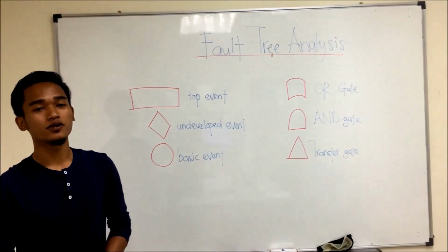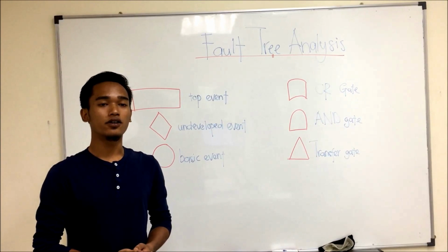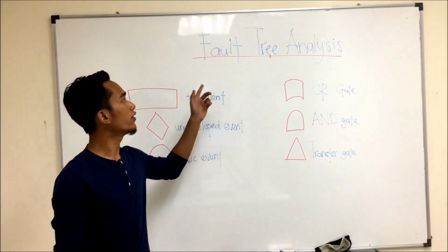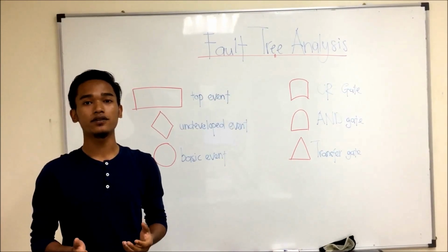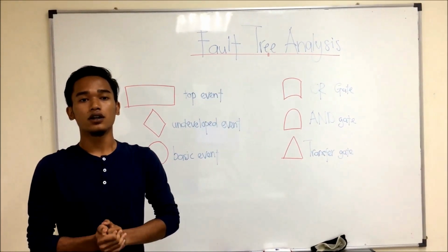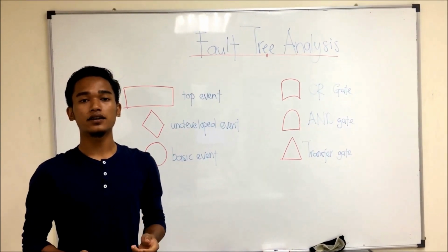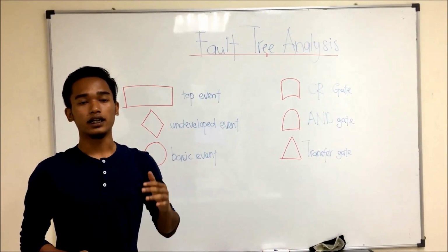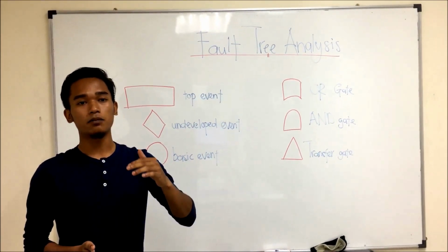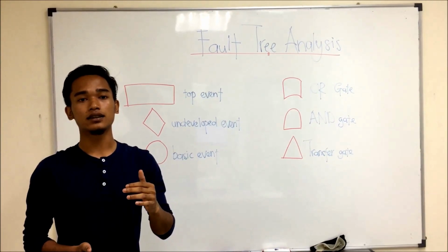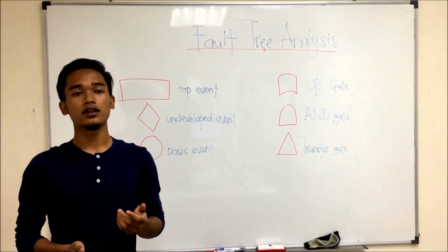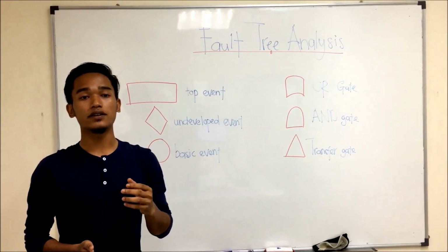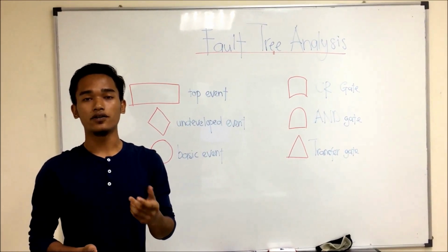Okay, another method we use for identification is fault tree analysis. Fault tree analysis is a deductive analysis approach for resolving an undesired event into its causes. This is achieved by a backward-looking analysis, looking backward at the causes of a given event to exhaustively identify the cause of the failure.